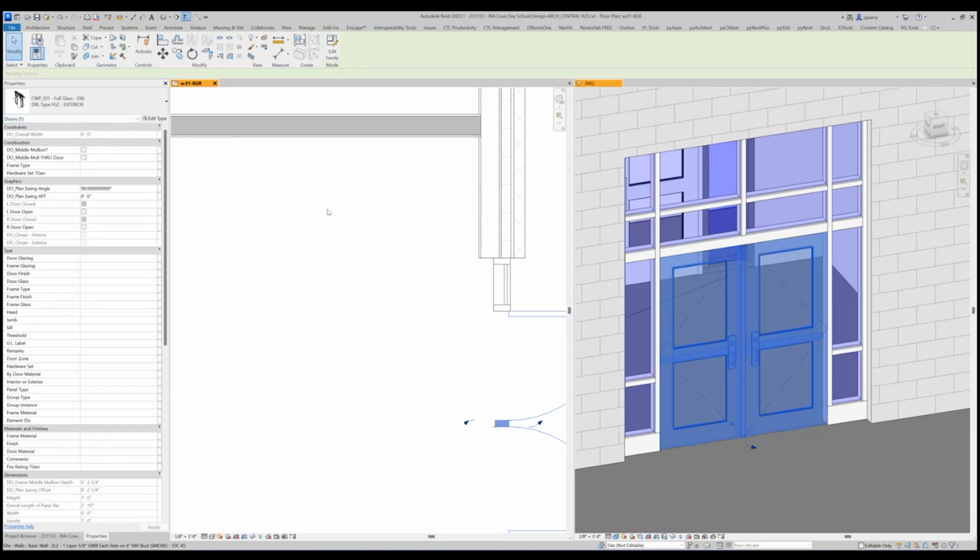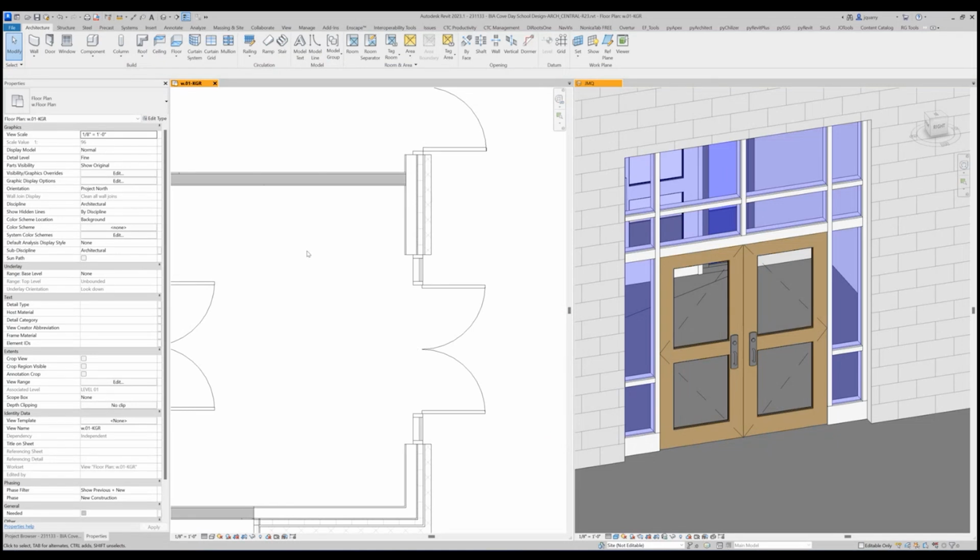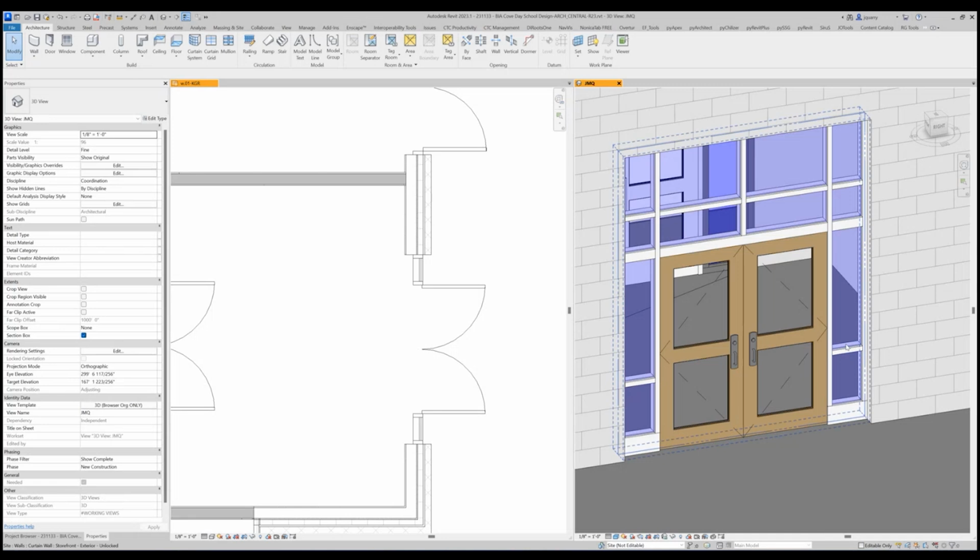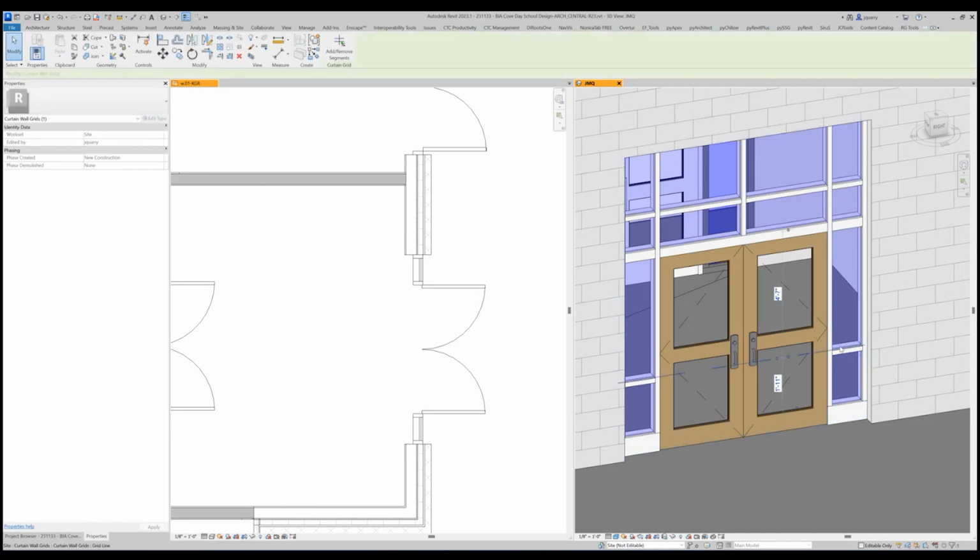So when you did the 1'11", did you do that from the top of the 8 inches? Yes. But did you do the top of the middle mullion or the center of the mullion? The center of this mullion. Okay, so the top to the center, because in the drawing, in that frame type, that's exactly where they did it. That makes it easy. Whereas normally you'd have to do math, right? You probably leave this down here at the bottom, and you'd know you needed it at 2'6". You would not need to know that now I got to put it at 2'7".